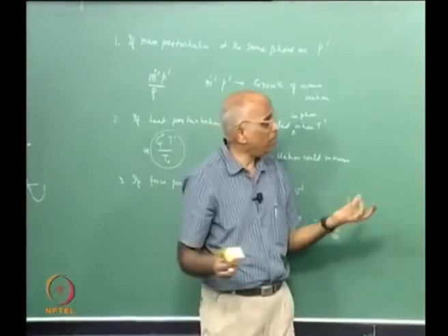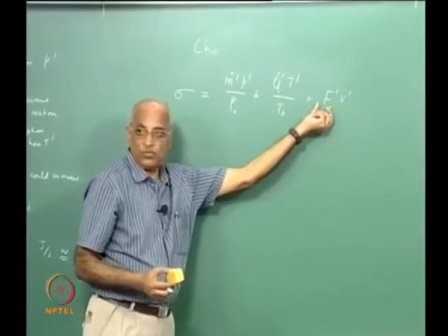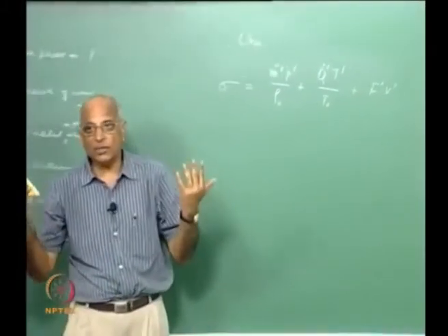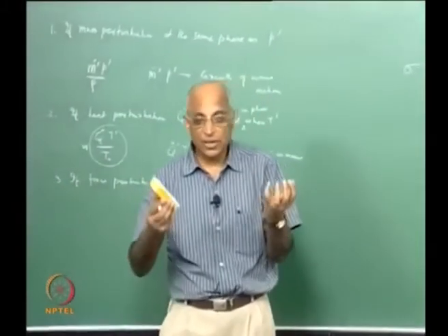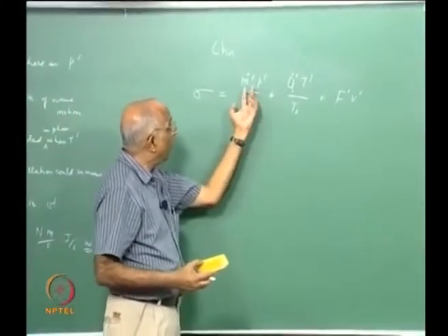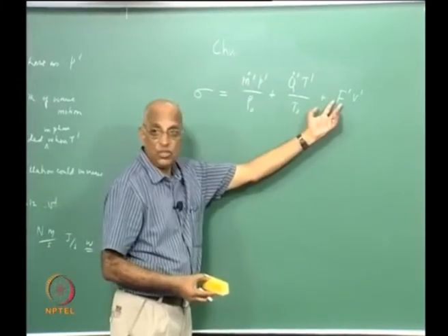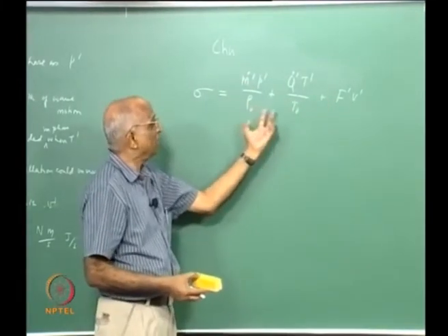And how do you put power? It could be from mass, it could be from heat transfer, it could be from rate of change of momentum, and we have all the three things in a rocket motor. We are generating heat, therefore heat could excite the oscillation to grow, we could have mass being added, we are adding force, we are having rate of change of momentum, it could add.